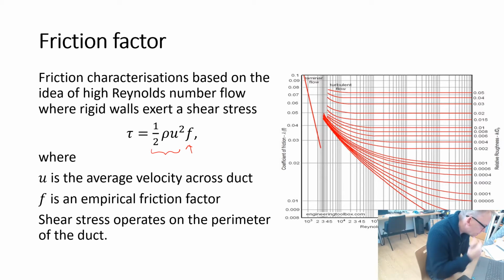It's empirical. Actually, there is a laminar approximation that you can calculate that you've done in year 1, looking at the drag on a viscous flow in a pipe. When we're looking at turbulent flow, there is the Reynolds number associated with flow in the pipe, usually UD over kinematic viscosity.